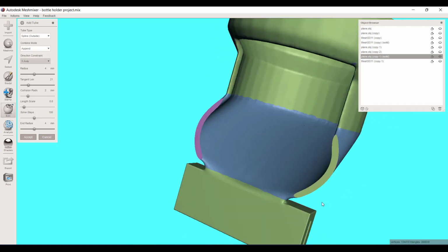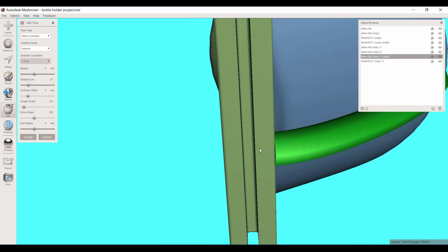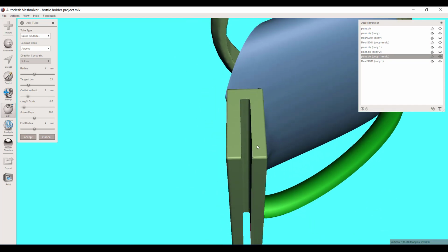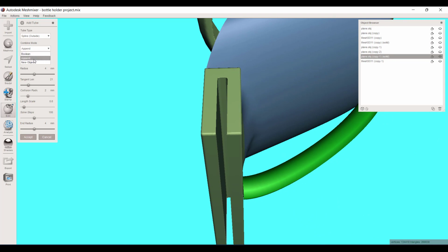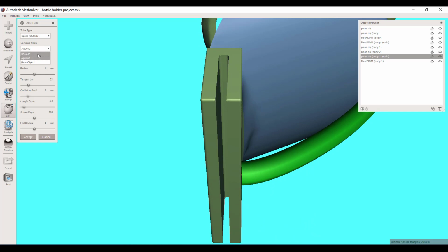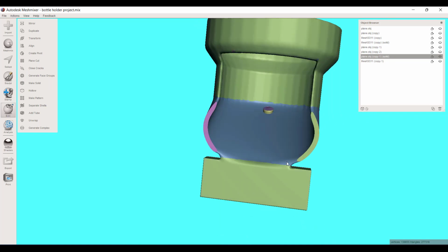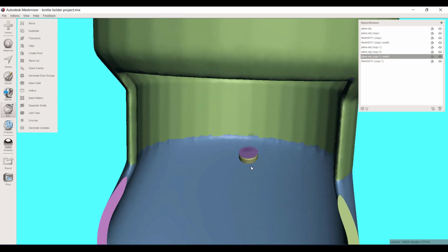One of the things when you use the add tube features, sometimes you'll get a little extension off of this, in which case it's better to create a separate object, new object, and that way you can just plane cut the ends of this into the interior of this portion and that portion. But here I don't see anything poking through, so I'm going to just say Boolean and accept it. All right. See, it did it here.